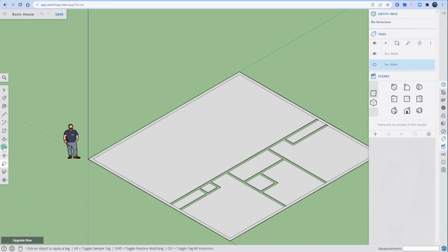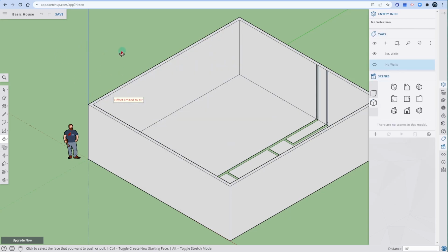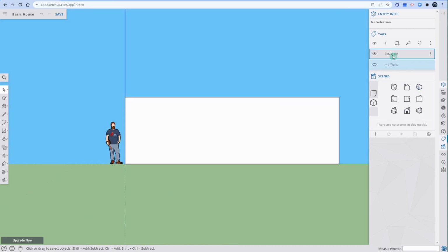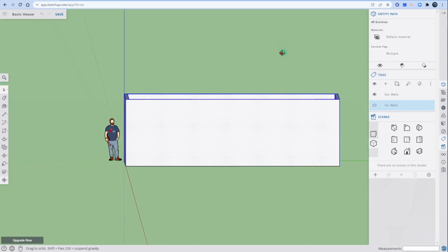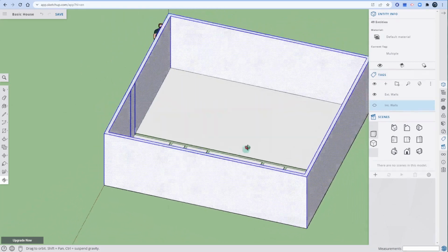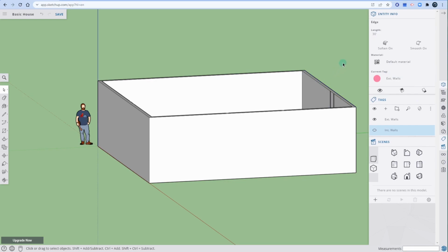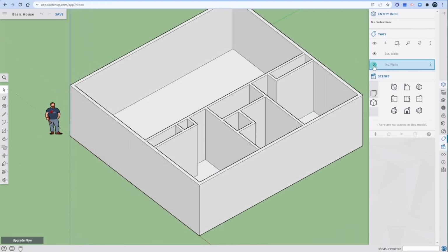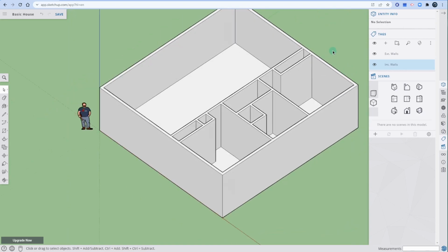That's fine down there. I'm going to press pull my exterior wall now. Ooh, pull this all up. Limit offset 10 feet. Fine with me. Set as 10 feet. I'm going to go side. I'm going to highlight all these guys. Now I'm going to... why isn't that letting me? Oh, because some of those walls are interior. Can I just choose it this way? Oof, rough. Just leave it. We'll turn tags on and off. Tags on a shape are funny. Just leave it. There we go. Interior, exterior walls are pulled.